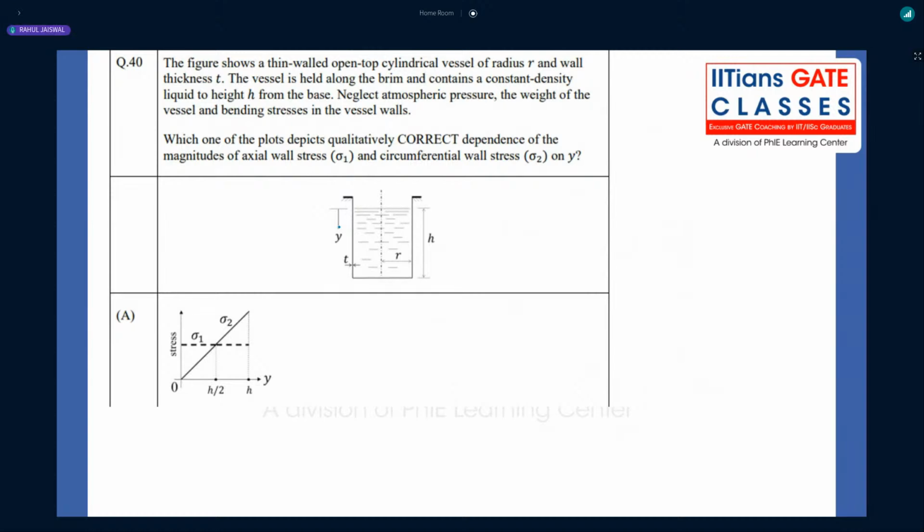Now, when you think of the next question, a thin wall case. This is basically a complete extension of the GATE 2008 mechanical paper. In that paper also, they had clearly mentioned one hanging thin cylinder, right? And there they mentioned how the hoop stress and longitudinal stress at a particular point, number one here and number two here, right? So this particular question is testing that only, nothing much about this question, right? You just think of this.